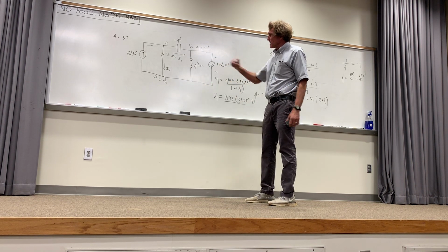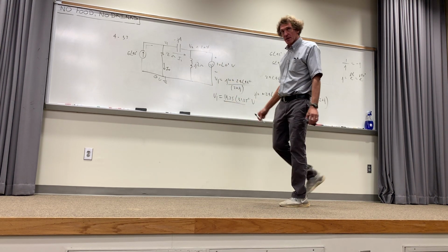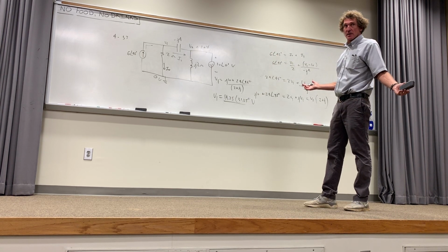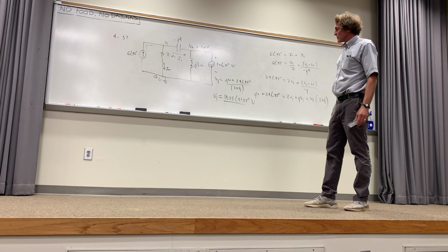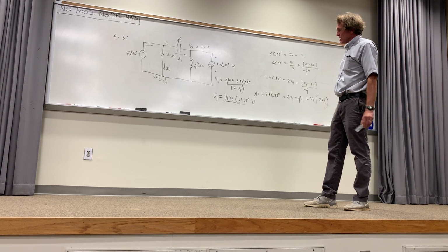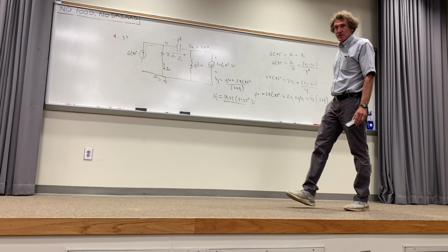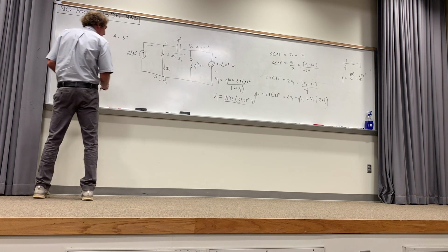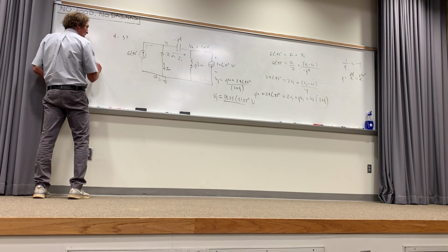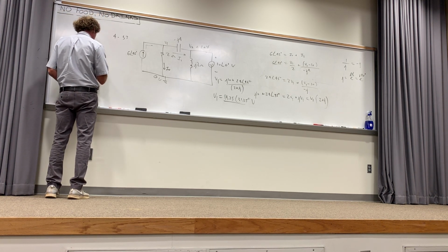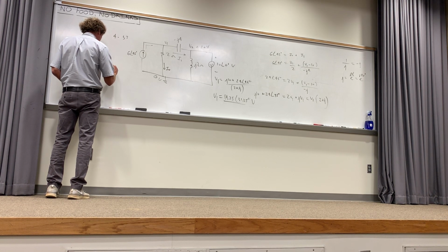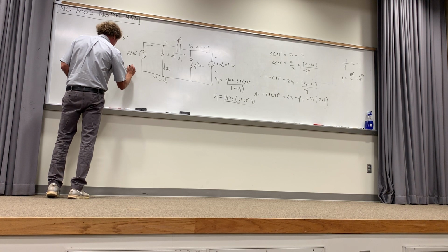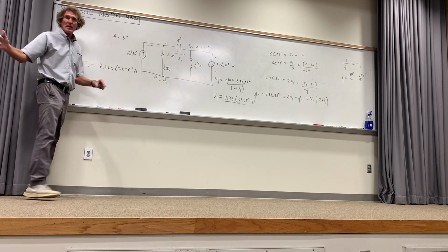By the way, what would the current I naught be? That's what they asked for. Class? If that is V1, what is the current I naught? It's just going to be that voltage over 2, so the current should be 7.125 at an angle of 31.25 degrees. Is that the right answer? Whoever asked me, did you get I naught equal to 7.125 at an angle of 31.25 degrees amps? Who asked me this question?